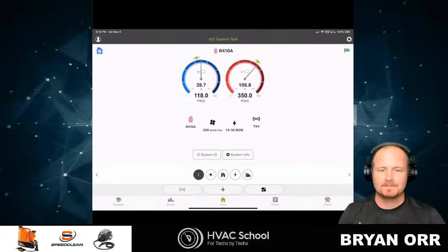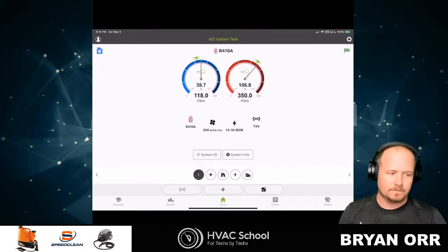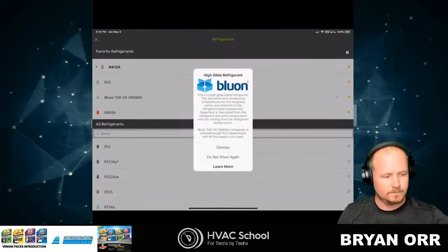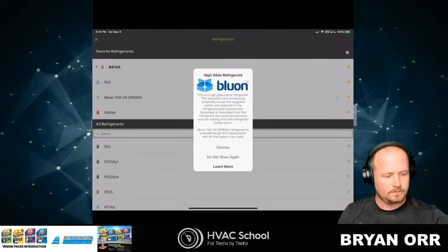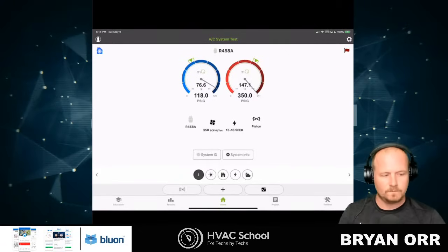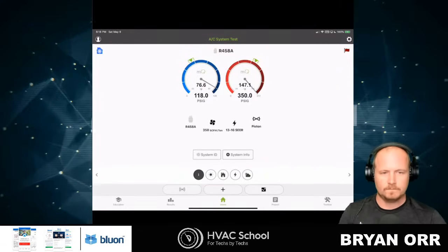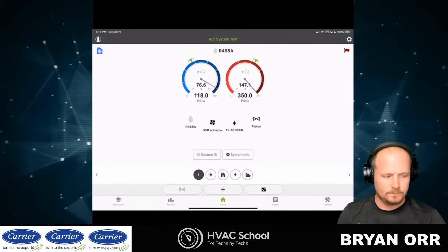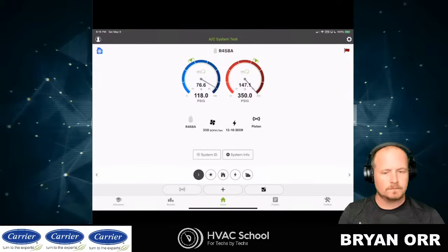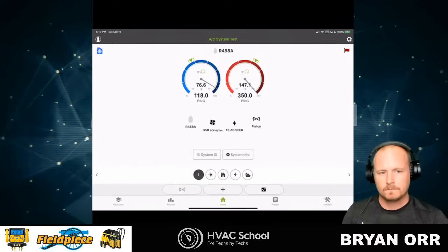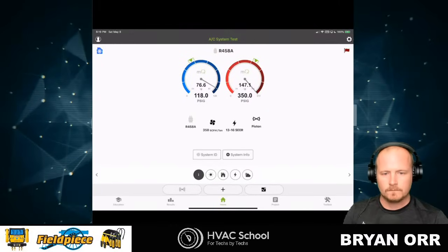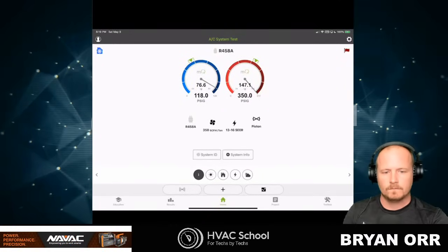In MeasureQuick, we actually show the center of the glide for blended refrigerants. For pure refrigerants, it actually is a saturation temperature. Because we're calculating coil temperature so we can calculate the targets, we show the center of the glide, which anybody doing refrigeration work wants to see on a refrigerant. Then we use dew point and bubble point respectively for the superheat and subcooling calculation. So the saturation temperature on MeasureQuick is not going to agree with your Danfoss slider or something like that, because we're calculating the exact center for the condenser and the weighted center for the evaporator coil.